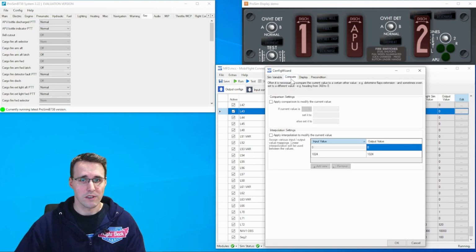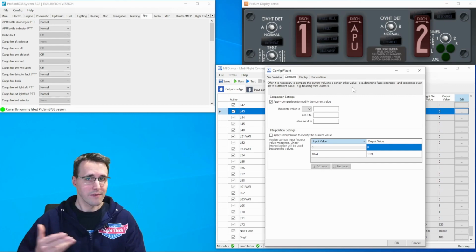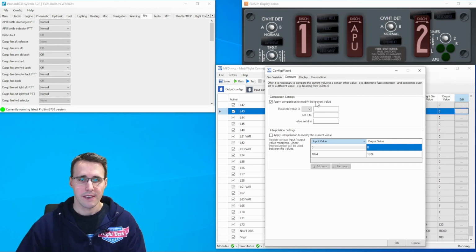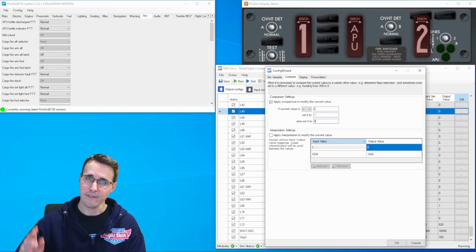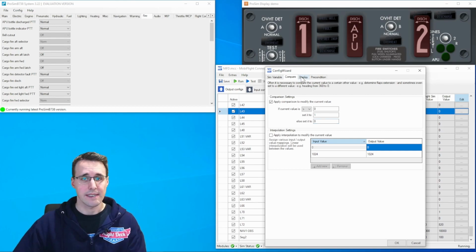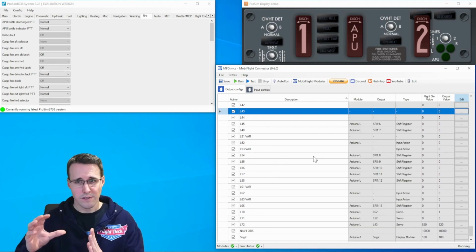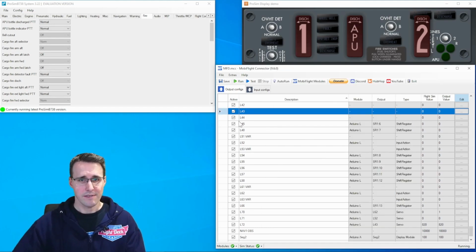Again, I will do a comparison because bit number 2 will bring us a different number than 0 or 1. And so again, if the value is bigger than 0, then set it to 1, otherwise set it to 0. So I make sure that I only have 0 or 1 if the unlocking mechanism should be opened. And again, on the display tab, do nothing. So now we have all our 3 informations that we need here all together in our output configurations tab.